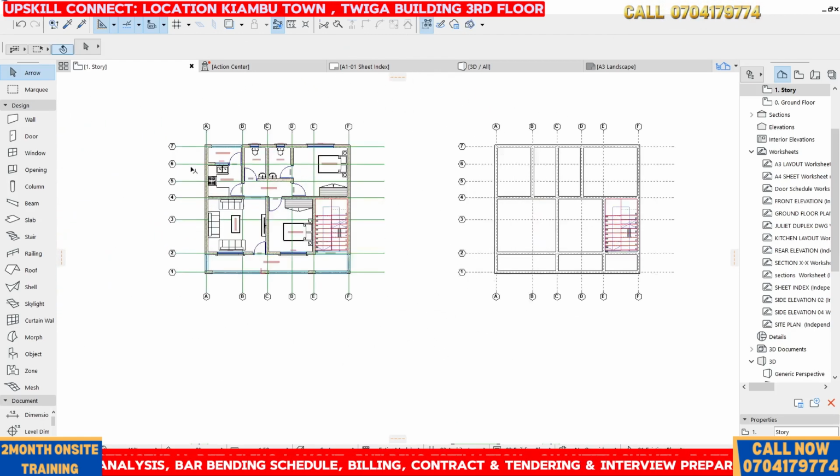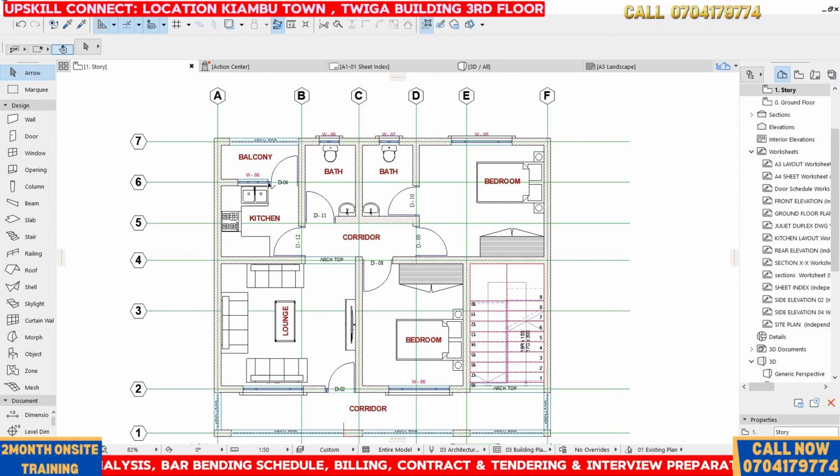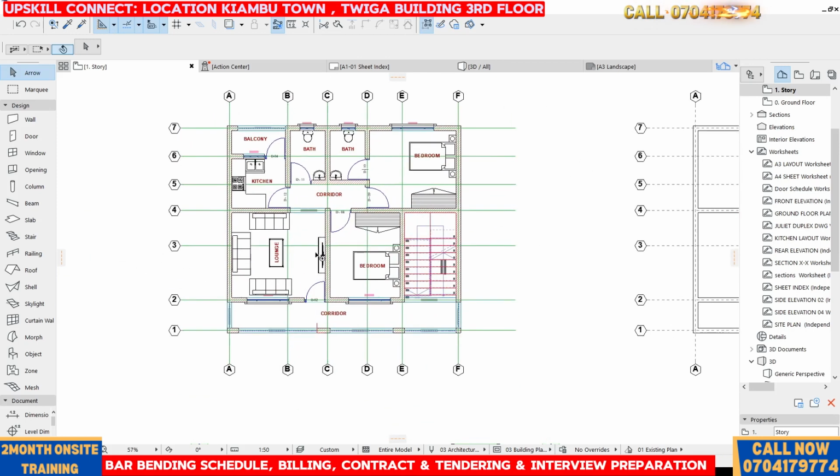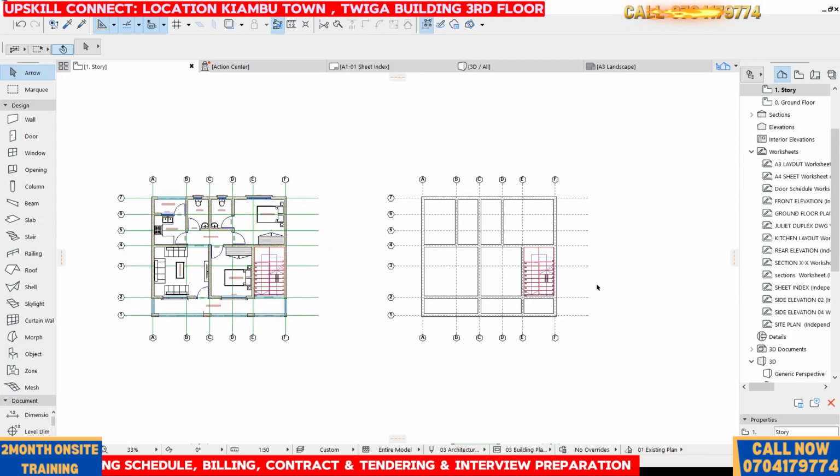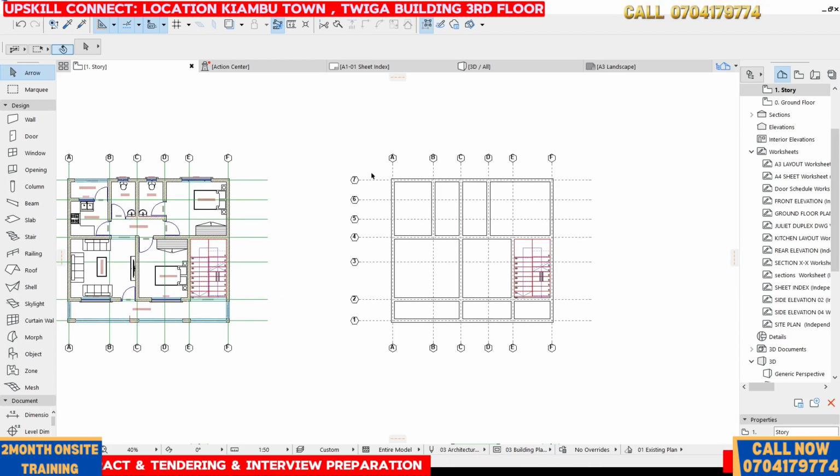So we have said that here we're going to put a lintel. Also here we're going to put a lintel. Here we're going to have a beam, we're going to have a beam here, probably another beam here. And here we have extended this because we're going to have columns. It's most important that you connect your columns to beams.